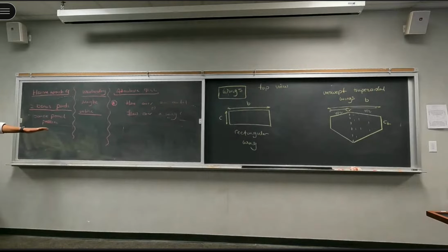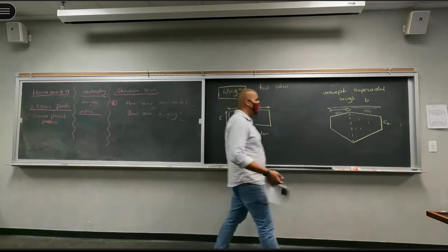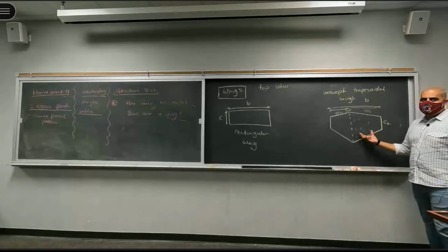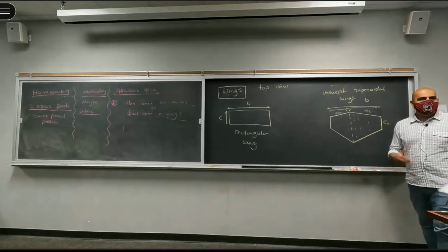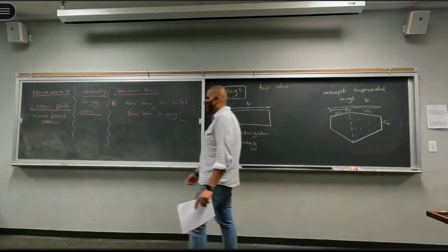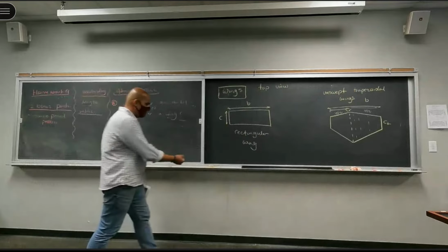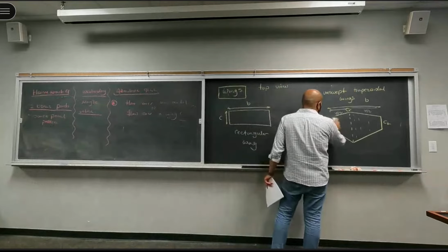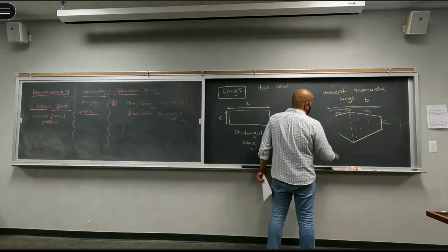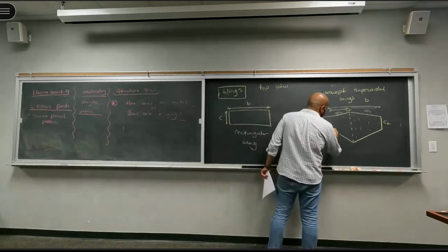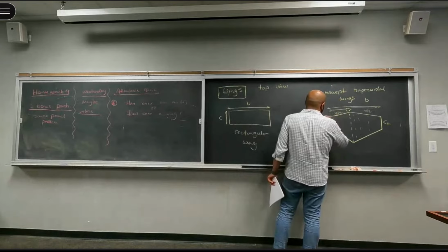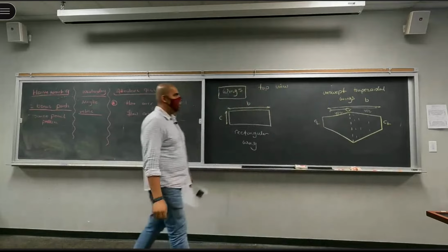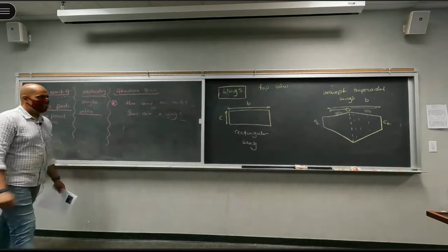So you're flying with a wing where this side is half of the other side, right? What will be the problem? You have more total lift on one side, right? So you constantly will have a moment in this direction, right? So stability is out of the picture here. There's no way you can fly this without any problem. I guess it wasn't a bad discussion to have, but you just have to make sure that you have the same length from the roots.